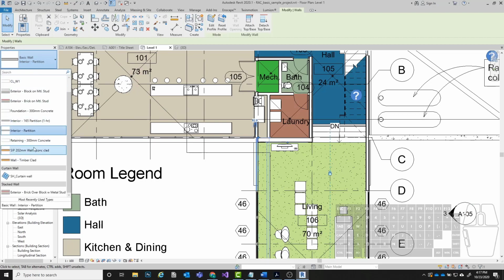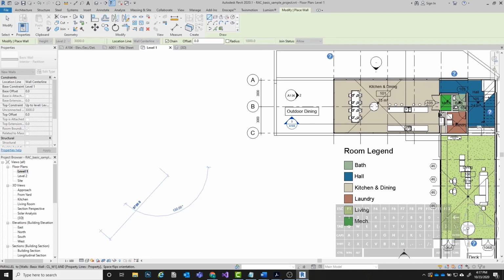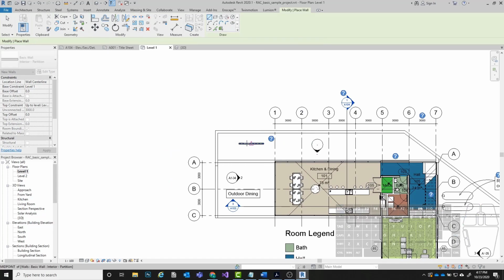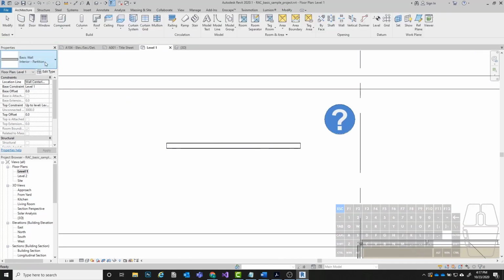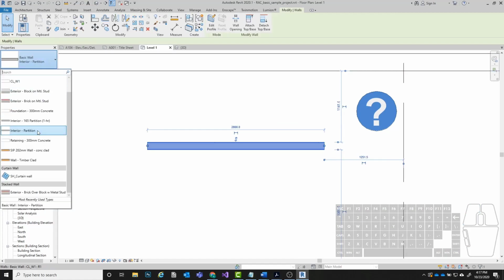And basically you go in and you have this menu over here where you add in these wall types, and you can click on them, and if you were to draw these in, it might not let me here. If I were to draw in a wall type, you can always go in after the fact and modify the type of wall that you're dealing with.